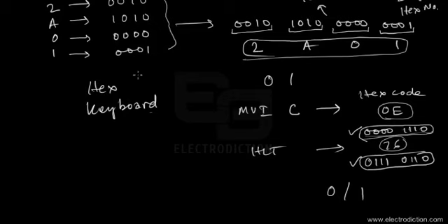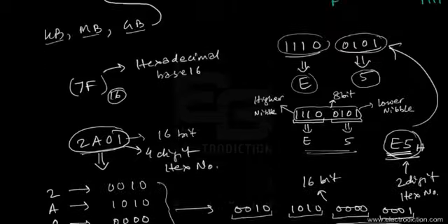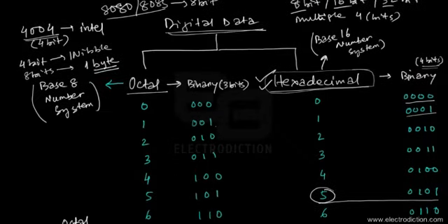Since you're using a hex keyboard, on the other hand, you can just press a particular switch. Let's say you enter this entire code by pressing 0 once and E once. That saves you the effort of pressing the switches 8 times, since you're entering an 8-bit code. So this is where the hexadecimal number system actually comes in handy.